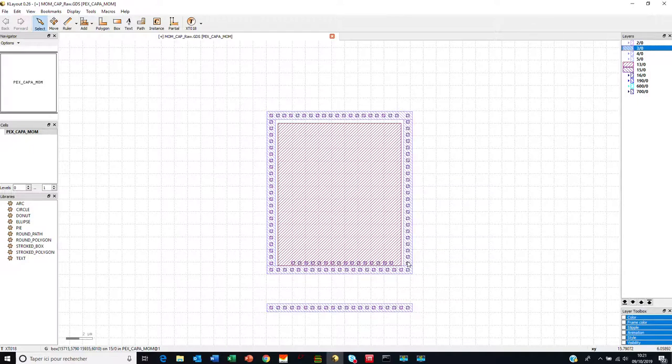The trouble is that when it comes to 3D, these two types of contact share in common their top z-axis coordinate, because it's just below metal 1, but at the bottom, active and poly are not located at the same z coordinate. So in fact, we have to split the contacts between two layers, one for contacts on poly, one for contacts on active.